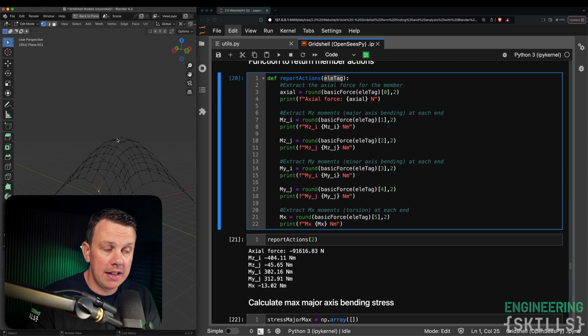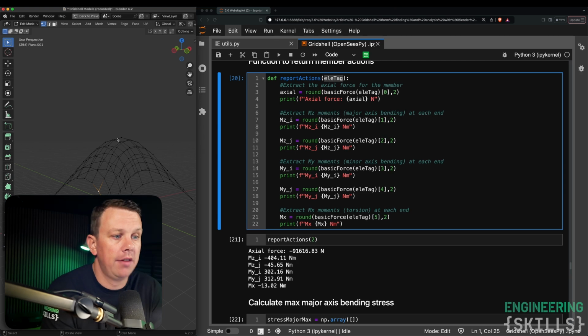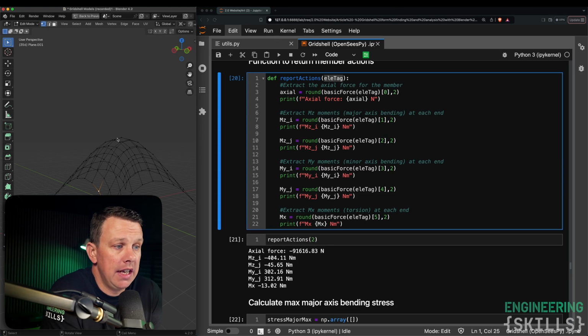And that then raises the next question, which is, well, what's optimal? How would you define optimal? There are a number of different ways we might think about this, but one reasonable way that we might approach it, that is quite straightforward and still directionally correct, is to say that optimal is the structure that experiences the lowest bending, or the least bending, okay? Because bending is an inherently inefficient way to use your cross section by comparison to axial force. In axial force the entire section experiences the same magnitude stress, but in bending, the normal stresses due to bending are larger at the extremes of the section, and they vary linearly, as you know, for a bending stress distribution. So we might say to ourselves, well, the optimal structure would be the structure that experiences the lowest bending stress.